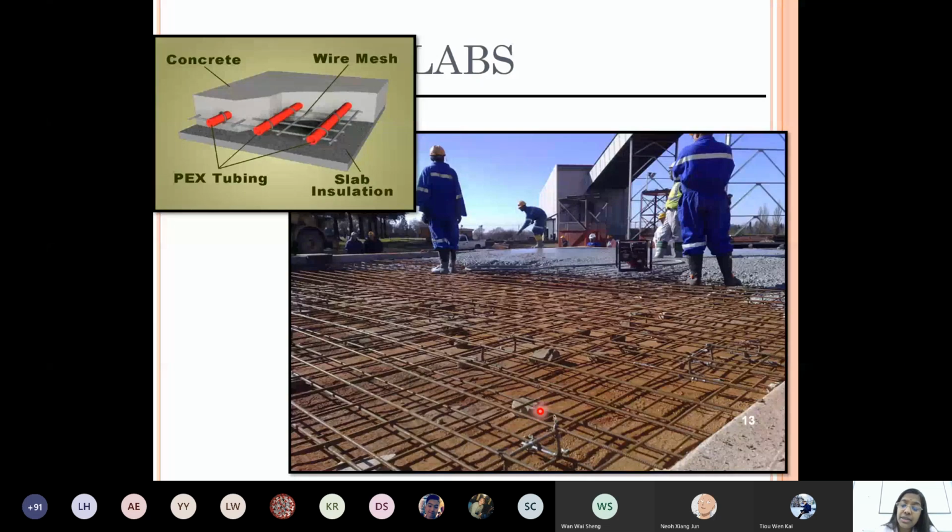They keep this cover and then pour the concrete so that when you finish, the reinforcement is not seen outside, right? When you finish your concreting, either slab or beam or column, the reinforcement should be inside. It should not be protruding out. When it is seen outside, you know the effects, right? It will get eroded because quite often we get rain. Due to rain and other effects, it will get eroded, causing problems to the structure. In due course of time, it can even collapse the structure. It will leave space for honeycomb, blowholes, all types of problems will arise later on.